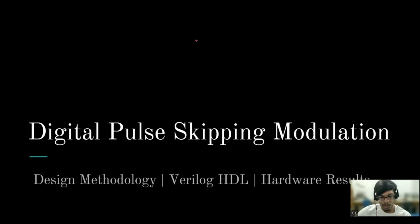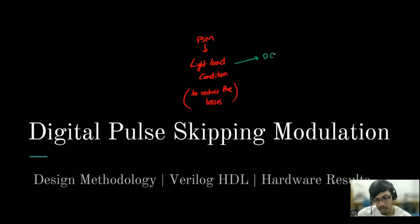Now coming to the pulse skipping modulation, PSM. Why do we use this? We use this in light load condition, to reduce the losses. And this is a DCM operation. So current will touch 0 and it will remain at 0. The waveform, you can say, is something like this.